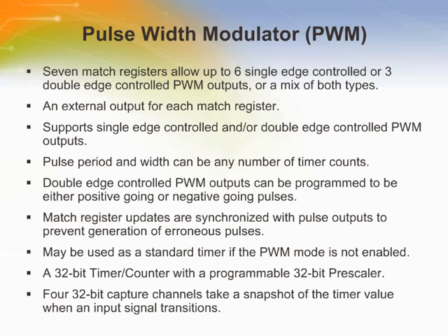The pulse width modulator, or PWM, is based on the standard timer block and inherits all of its features. Although only the PWM function is pinned out on the LPC214x series, the timer is designed to count cycles of the peripheral clock, PCLK, and optionally generate interrupts or perform other actions when specified timer values occur, based on 7 match registers.